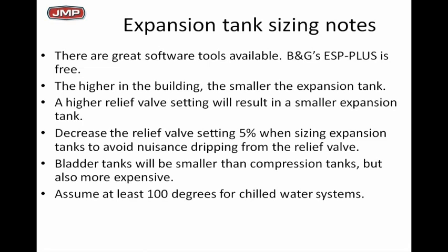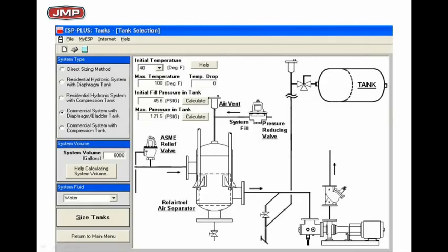And if you've got a big system, like a university system that's huge, you might drop the 100-degree water down a little bit. But remember, what is the max temperature you ever expect in that system? And you also want to make sure you've got an expansion tank big enough to be the boss, to be the point of no pressure change. Also keep in mind, glycol expands at a different rate than water, and you need to take that into consideration when sizing tanks.